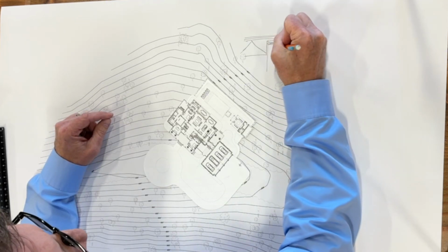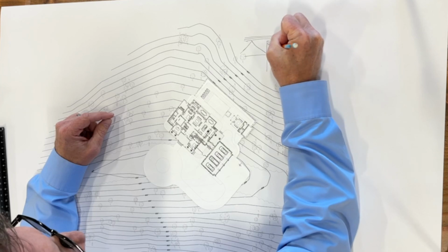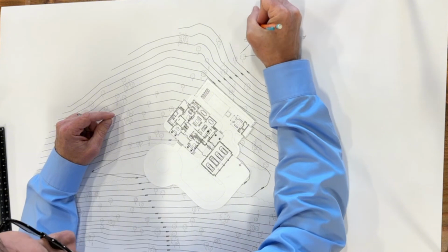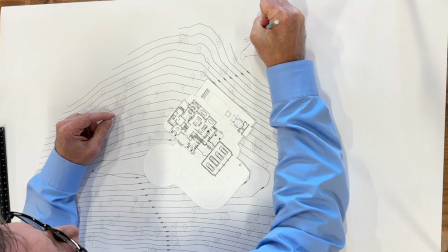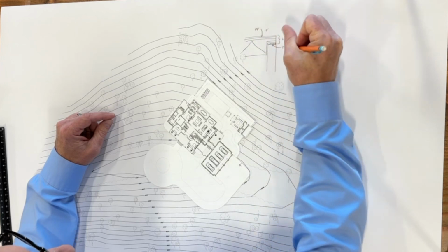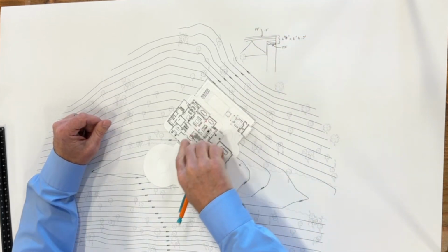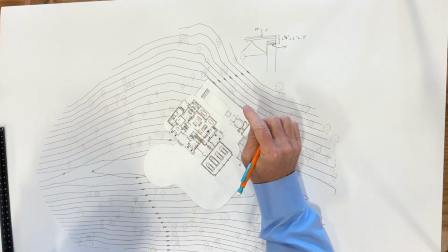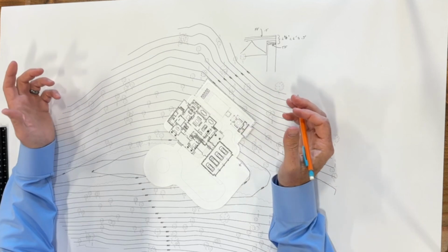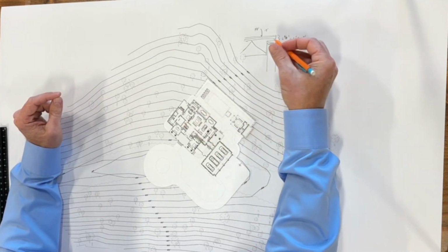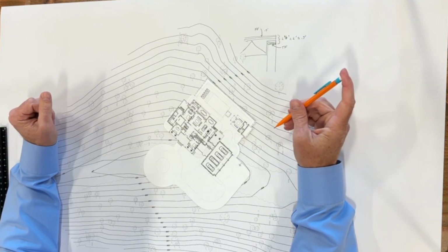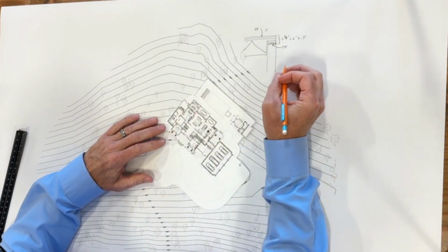Now, when we say top of foundation, TF, we're talking about the elevation at that spot right there, right? And then finished floor, FF, is right there, which we're going to say is 0.5 feet higher than that top of foundation. Because there's no walkout on the back of this basement, we don't really have to worry about how deep the basement is or what that elevation would be, because it just doesn't come into play. But if there was a walkout, then we'd be looking at BF, or where the basement floor is.